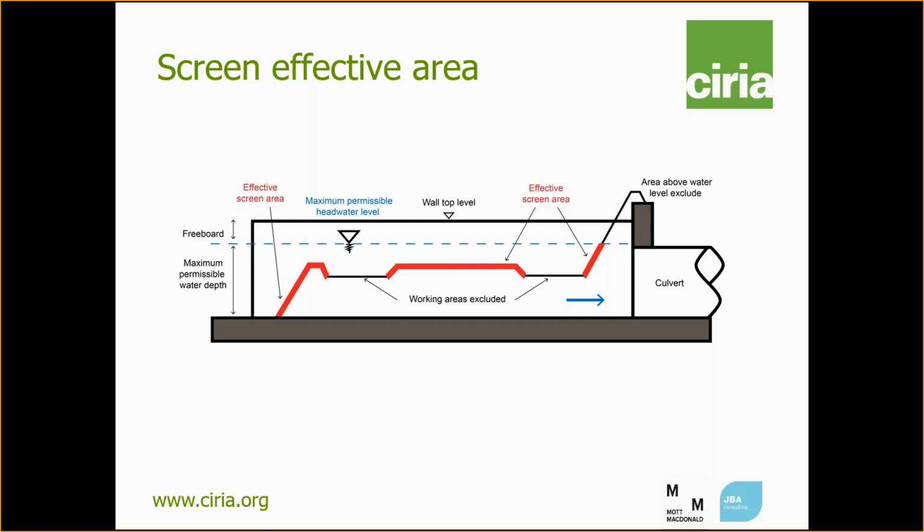have a 0.15 metre centre-to-centre bar spacing, and a ratio of 3 or more for debris screens, which have a wider bar spacing. And we would expect a larger ratio, a larger screen size, if the debris load is likely to be heavy, or if the screen could block before operatives are able to mobilise and remove material. But screen sizing is uncertain due to limited blockage data and factors such as land use and climate change.